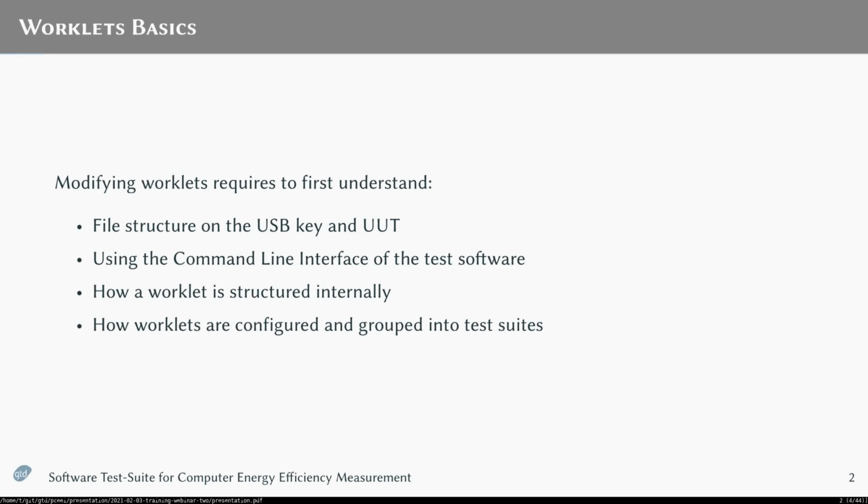Okay. For the worklet modification to be possible, we first need to understand a few things, which I will go into detail before I tell you how to actually modify a worklet. So we need to take a look at the file structure on the USB key and on the unit under test, so that you actually know where the files are you want to modify. Then we need to use the command line interface of the test software, because with the graphical user interface, you cannot do any of these advanced tasks.